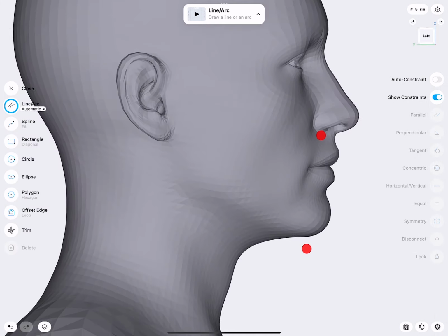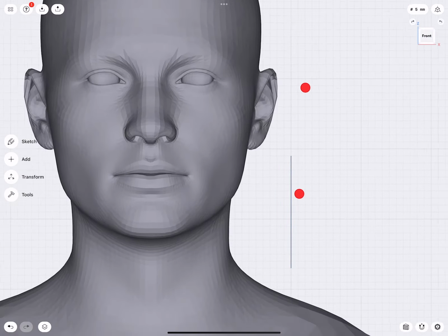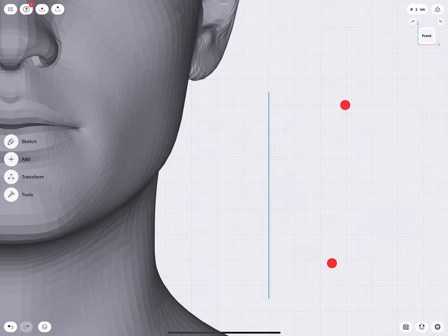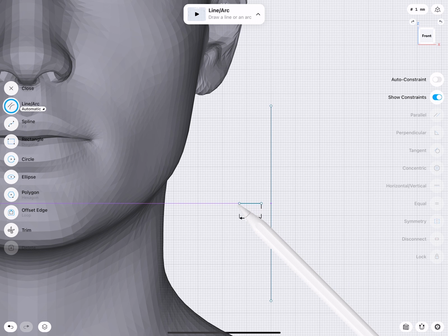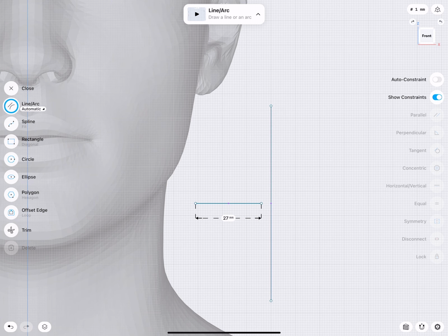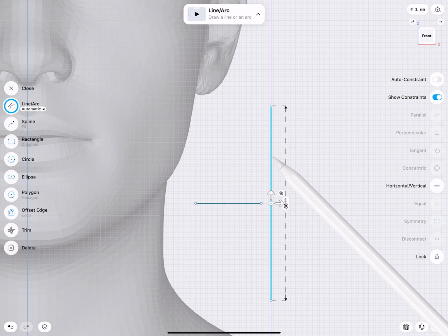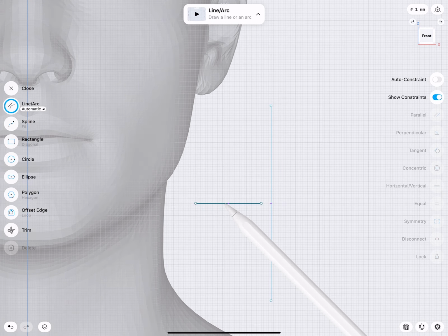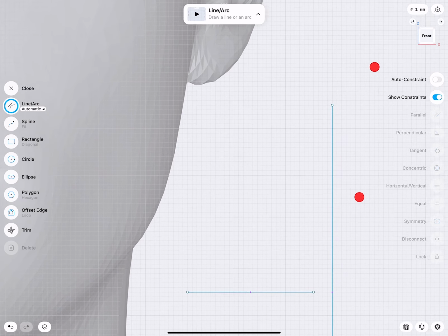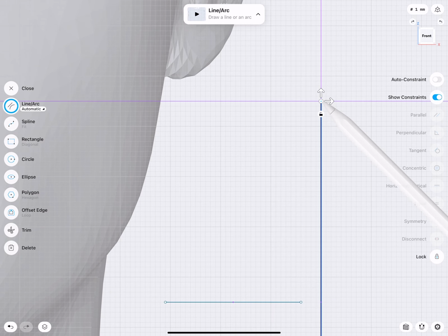So let's go ahead. Actually, we stay in the front view and then again, using the grid somewhere, I can figure out for making a nice ring, I need a circular profile and a revolve axis. Here's my revolve axis. And I used this midpoint of the vertical line to know where is from here downwards 40 millimeters. That's there, this position. Okay, so that means when I go up, here's my start point.